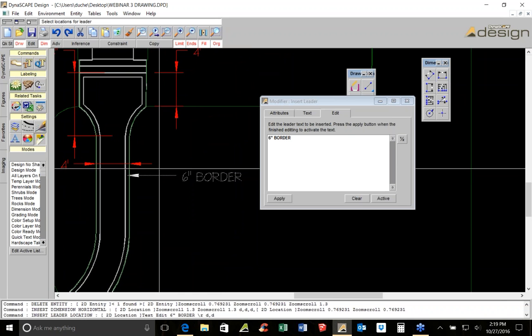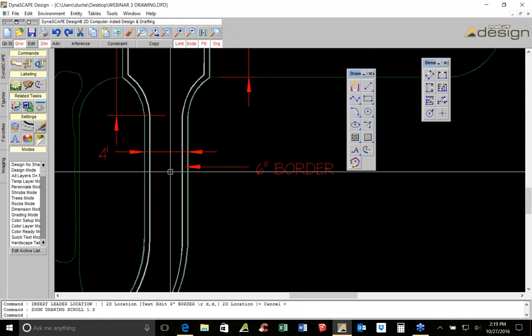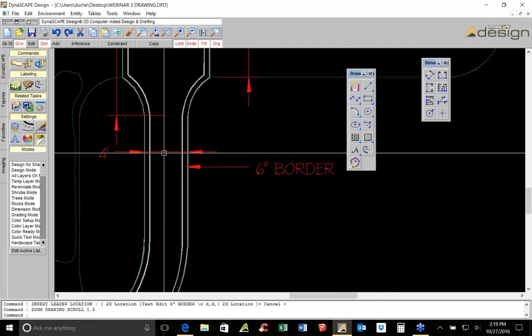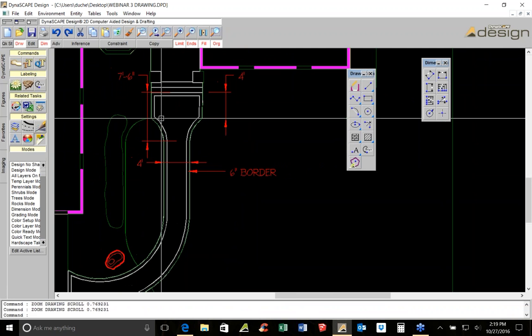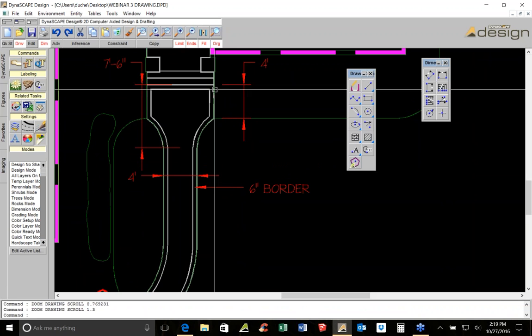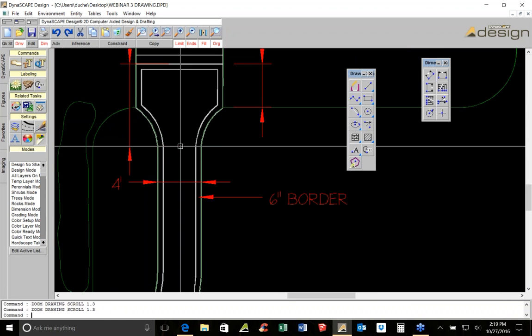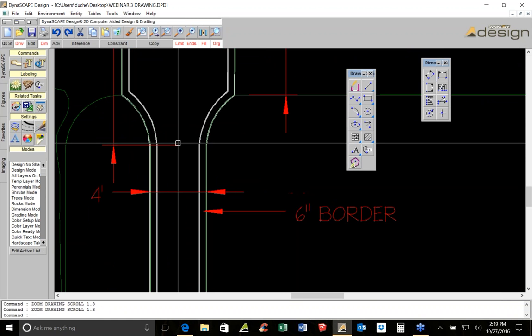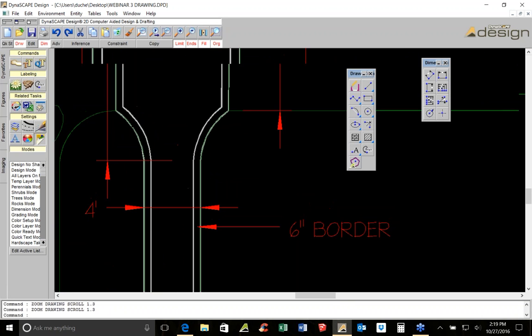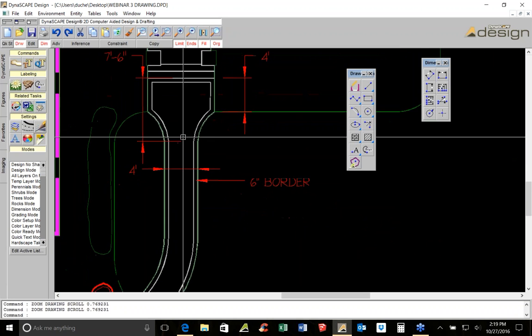So then they know this is a 4-foot walkway, but they have 3 feet of field because they have 2 borders at 6-inch. So if I sent somebody out there to the job, they could measure out 4 feet from each side. They could put a tick mark right here, offset this line by 2 feet because they know it's 4 feet, and just connect this radius.